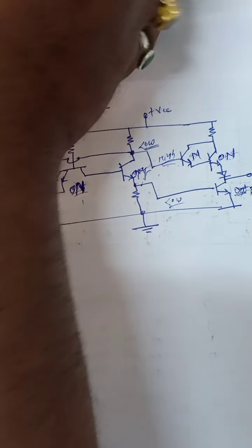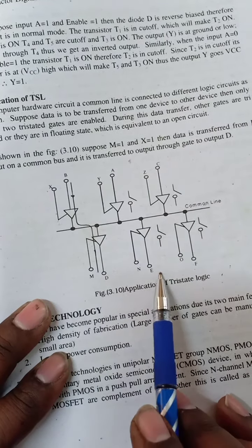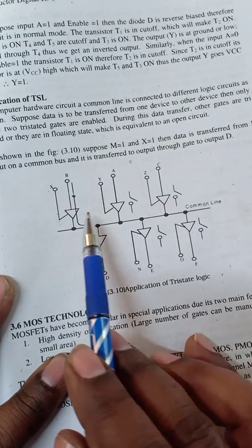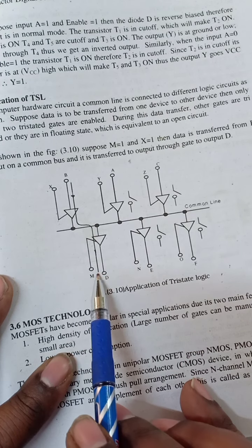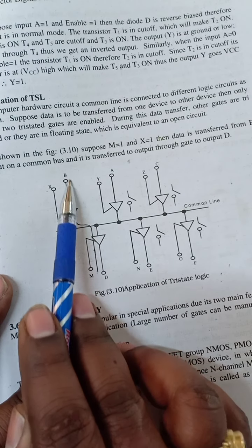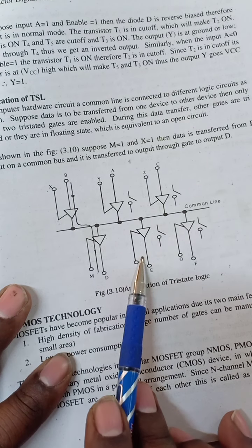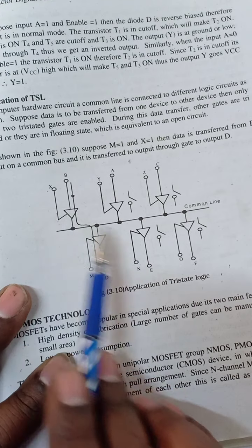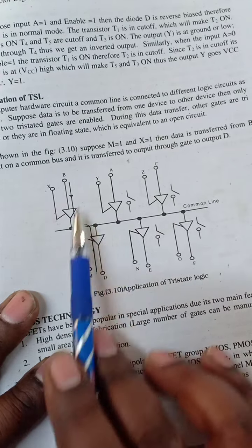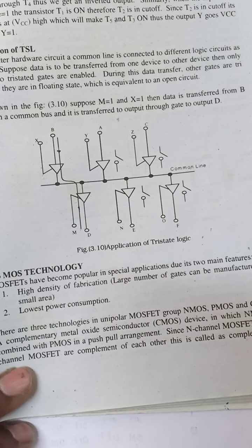Okay, so this tri-state logic is used in microprocessor circuits. In that case, this is the data flow, this is the input data. Suppose we want to route the data to here, this to here. In that case, you enable both of these so that it is routed here. If you want to route this incoming data to here, then you make these enabled so that this data will be routed to here. So such types of applications use the tri-state logic circuit. Okay, so now we are going to stop here.